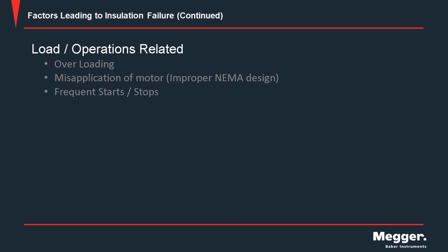Quite often we're either overriding protections or there's no protections in place to limit that, and operations might exceed the start-stop recommendations, and of course wear out the insulation prematurely. During starts and during shutdowns, that's where we experience the high voltage spikes I mentioned earlier.